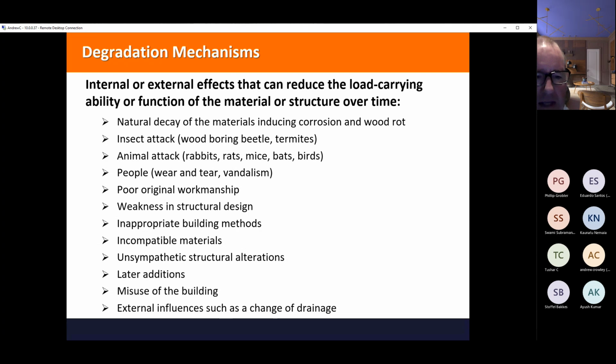Drainage around the building can have a big impact on the foundations. So if your drains get blocked, or you overfill or over-soak your area, it can have an influence on your ground and therefore on your foundations. And that will show through in the cracks in the building.